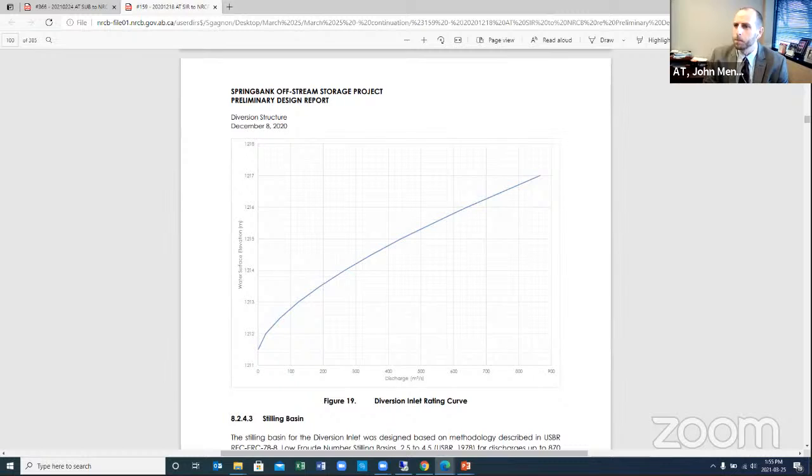In simplest terms. And in this case, what type of flow do we have? Primarily, it functions as weir flow for the majority of it. But as I said, if you were ever to get water surface elevations that would exceed the design, so for our intents and purposes, that 1215.8 is intended to be the 600.